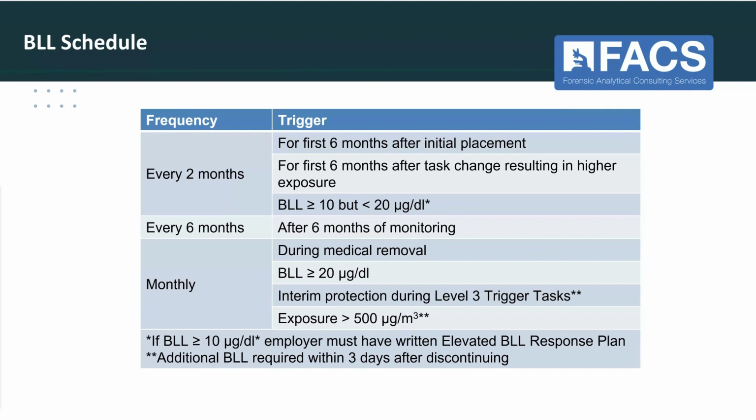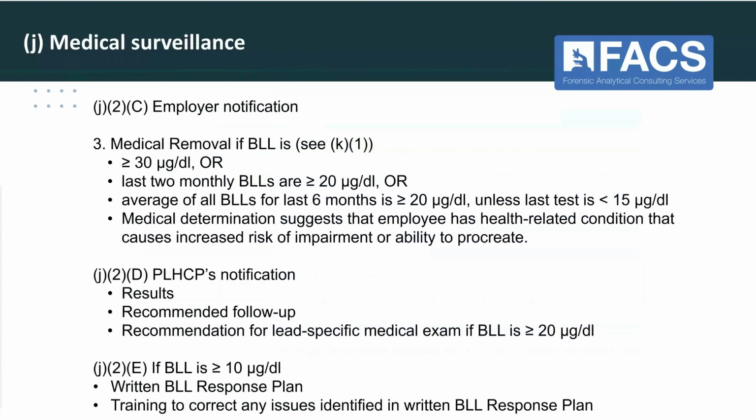And this is the only section where, as we started out early on talking about the definition of altering or disturbing, that definition applies. If I've got somebody that has to be medically removed, they cannot do any of that altering or disturbing work on lead-based paint. And again, this is the only place that Cal OSHA defines lead-based paint at 5,000 parts per million or 0.5% by weight.